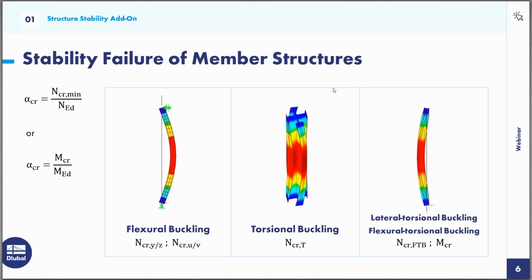So as we already know, we have this problem or stability issue of flexural buckling. So we have a compression force in the member, and then as a stability mode shape, we will get this lateral deformation. So there we have the critical loads, and critical for buckling around the principal axis or around the geometrically axis, so strong and weak axis, the flexural buckling mode shape.